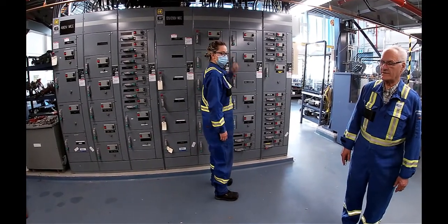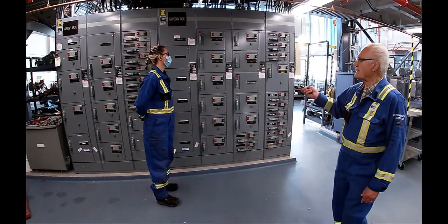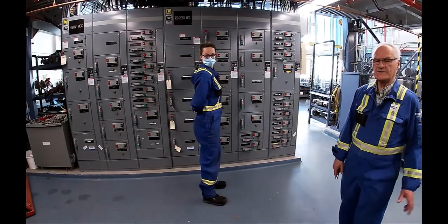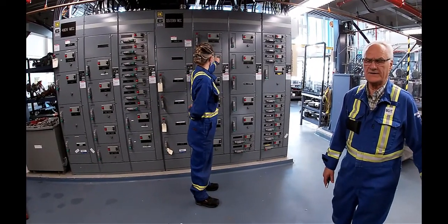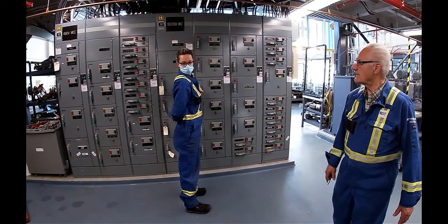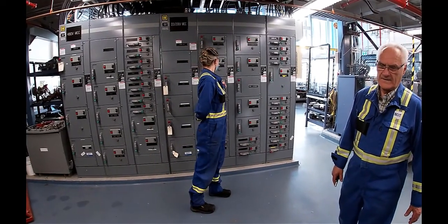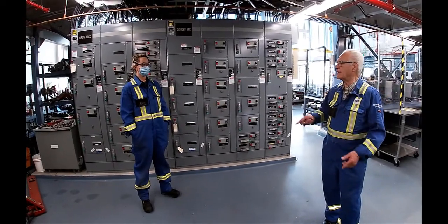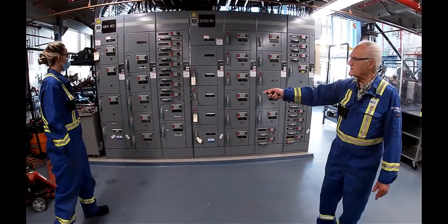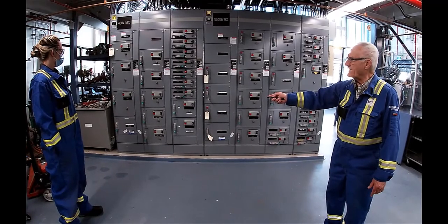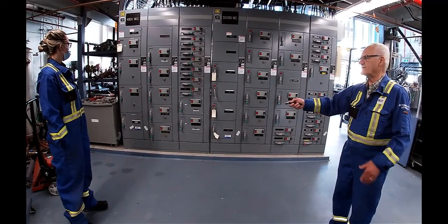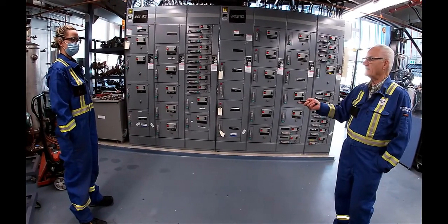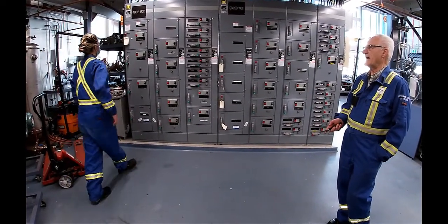And yeah, that's great. And the rest of these we will need later, so let's turn on agitator 5.2 and 5.3. These are the two big agitators in the stock tanks. Okay, so that's all we're going to need for making up the batch. Later on, behind you, we're going to turn on pump 5.1 to be able to transfer the stock from the heavy stock tank to the light stock tank. And so we might as well turn on that disconnect now.